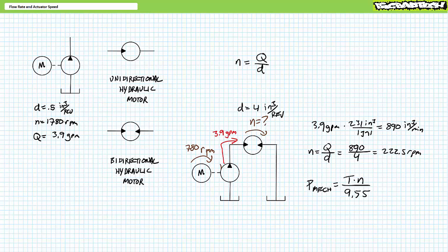We'll examine rotating mechanical power in greater detail in later lectures, but as a preview, mechanical power is a product of twisting force called torque, T, and rotational speed divided by a constant. It's obviously too much to ask of the real world, but consider a 100% efficient system where 100% of the high-speed, low-torque mechanical power output of the electric motor prime mover is converted into hydraulic power with a given pressure and flow rate by the pump, and then the hydraulic motor converts 100% of the supplied hydraulic power to low-speed, high-torque rotating mechanical power.